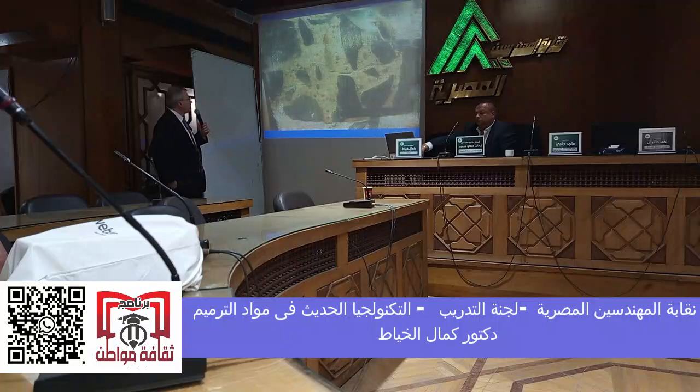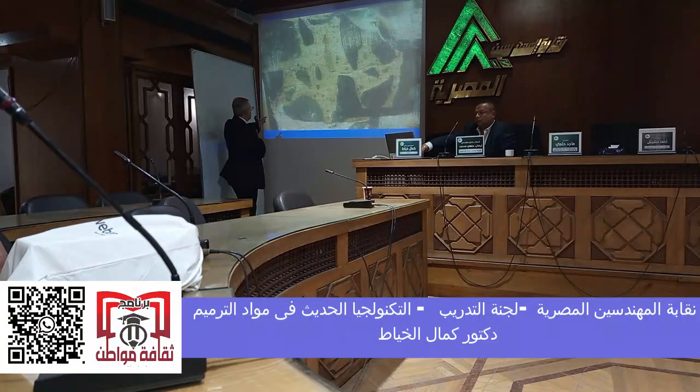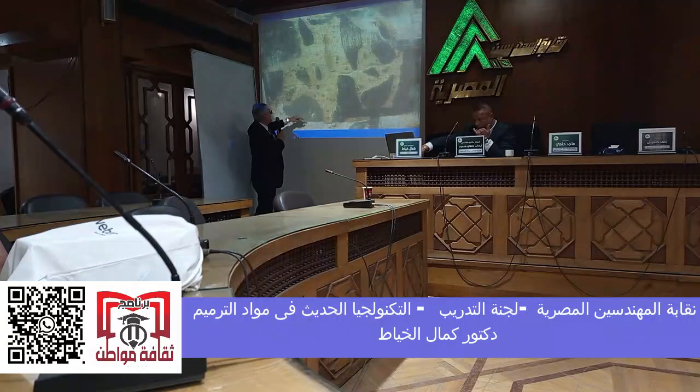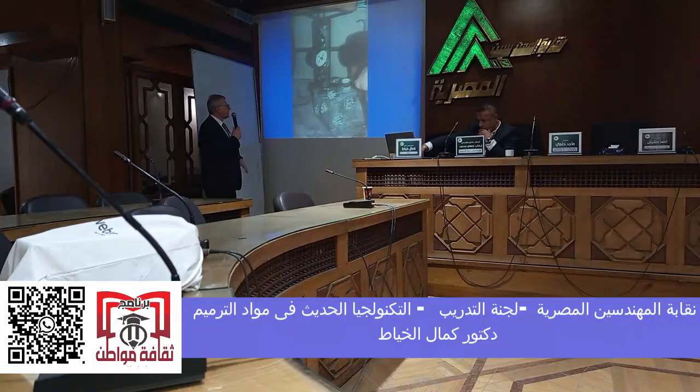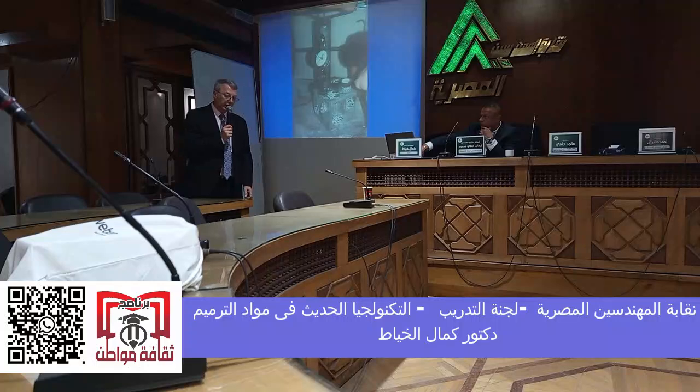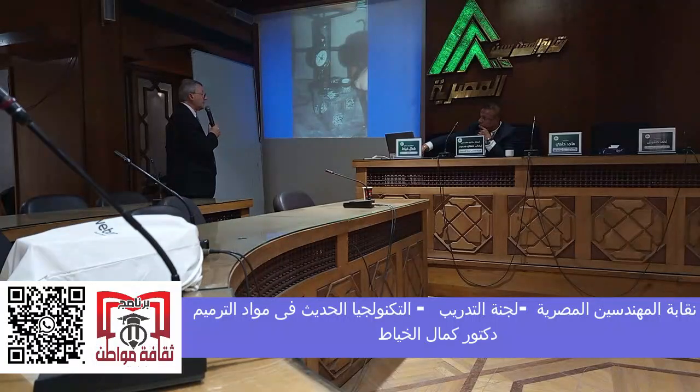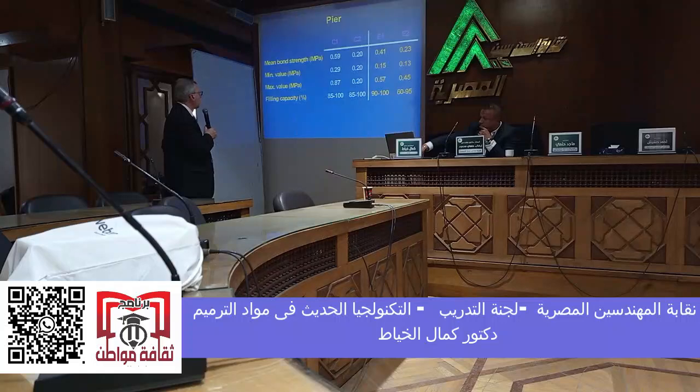And then we took some cores and looked at the repair. You see, this is a microfine cement. Next. We also did some pull-outs to test the bond strengths between the epoxy and the concrete, or the microfine cement grout and the concrete. Next.